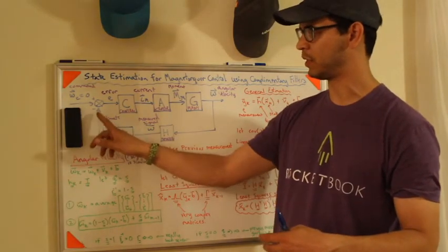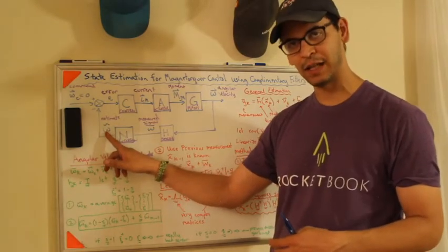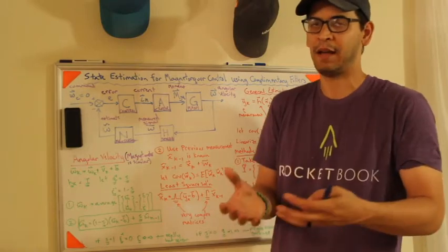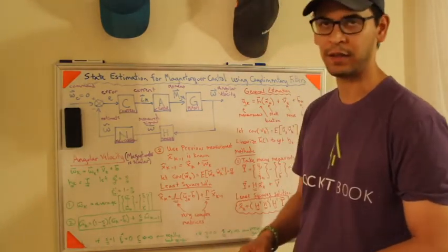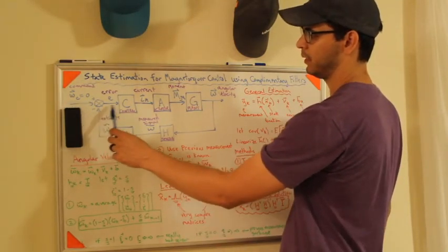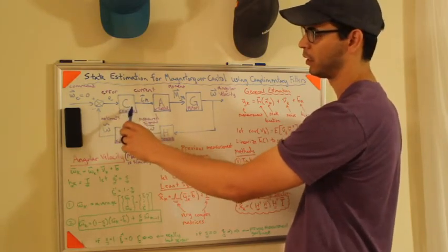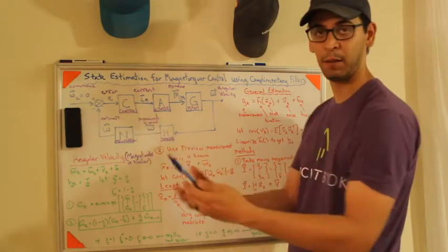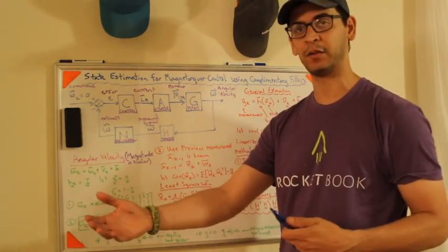I don't actually know how fast I'm spinning, I just have an estimate. Actually, I'll go ahead and mention this one branch here. This is my estimated angular velocity. Again, I don't know how fast I'm spinning, but I have a pretty good idea based on some measurements, and hopefully this complementary filter. That error signal, my command minus my estimate, is going to go into a controller. I'm going to have a separate video talking about this controller, but it's going to compute how much current in amps I need to run through the Magnetorquers.